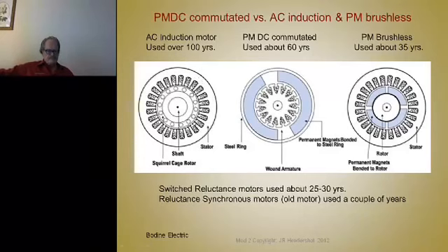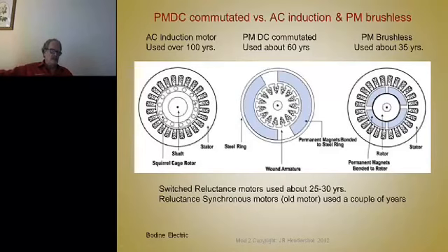So the current that flows into the stator magnetizes this circuit, and since it's an AC current, if you load this thing down, you're going to get some slip, and that means you're going to induce some current to flow into the bars here, which is going to create the right polarity of flux to give you a torque due to the flux linkage of the ampere turns from this field with the ampere turns from that part of this field.